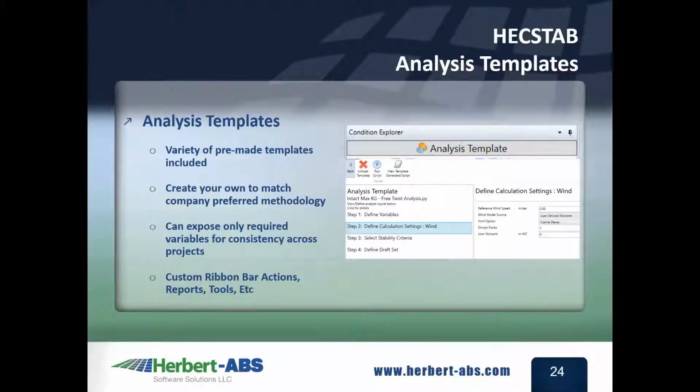Another nice new feature with the new package now is the idea of an analysis template. So we have designed HexTab to be very flexible and to do any type of calculation that you want. But in reality, a lot of analyses are going to be very cookie cutter. You'll be doing the same things for different models, but the same basic approach. Looking at putting together an intact required GM curve or damage stability required GM curve or something like that. So in cases like that, we designed it so that we can make an analysis template for that approach that will walk you through the basic steps to do that analysis.